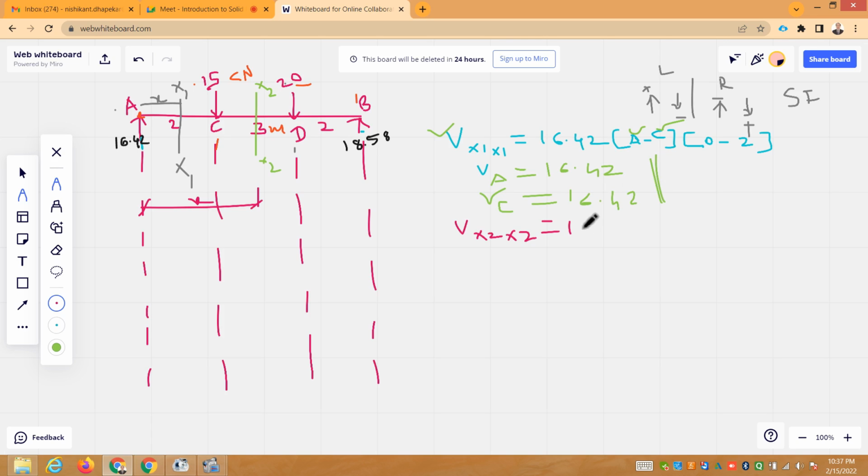In the shear force equation you have to consider only the forces. When we develop the equation for moments, you have to multiply by the lever arm and distance. Then next is this force in the downward direction. To the left of x2 this force is there. So section left downward is minus, so it will be minus 15. Your section is valid from C to D.